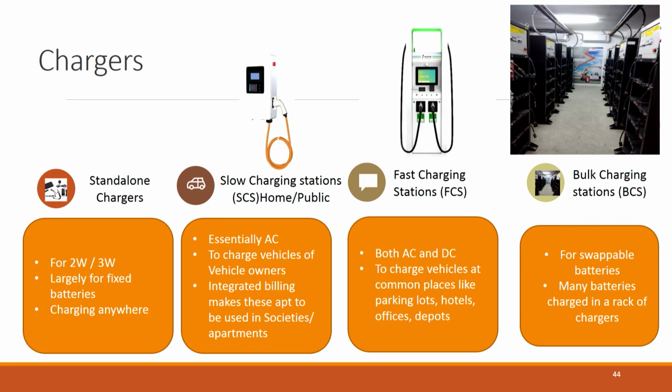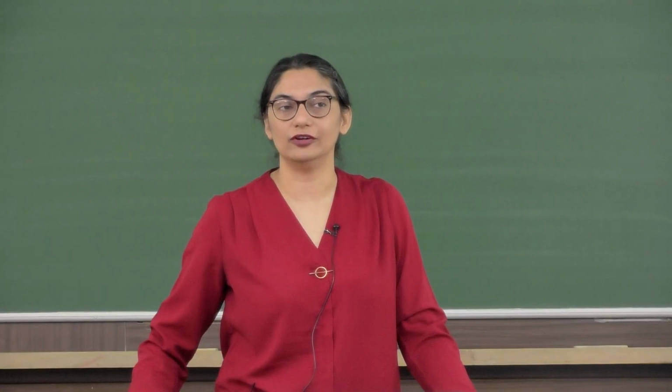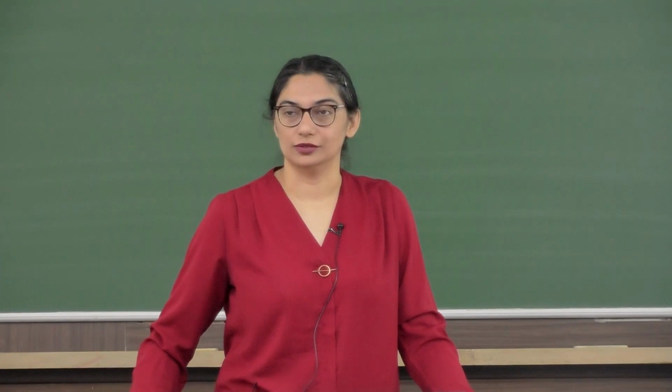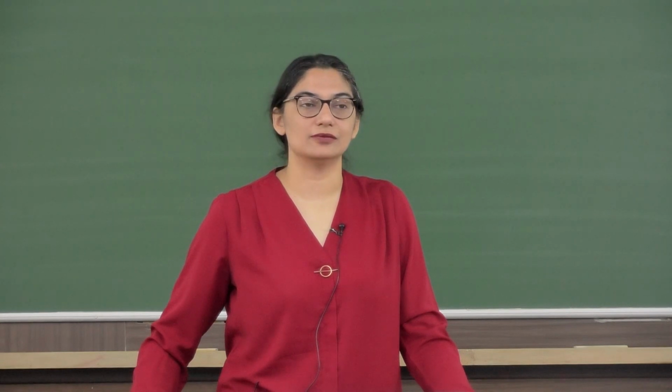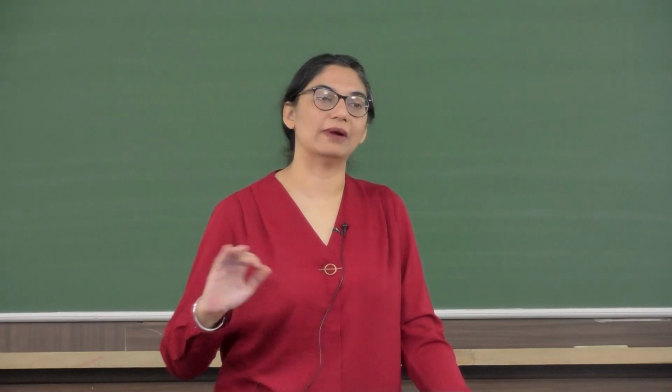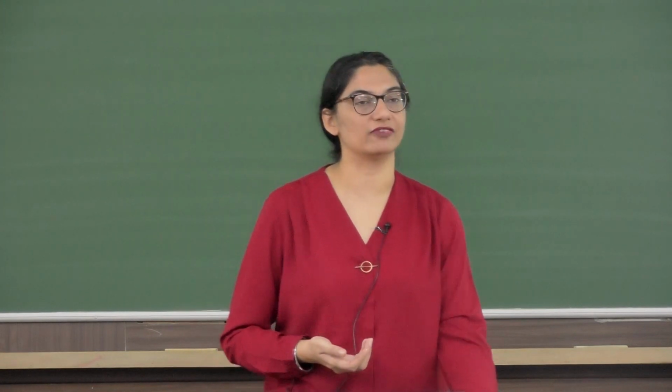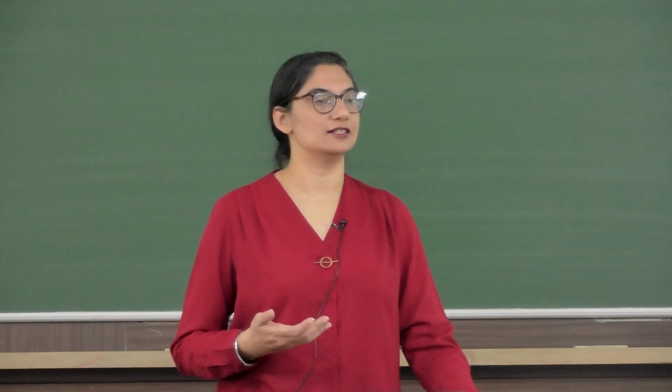But it also depends upon whether my charger is able to charge that battery at that rate or not. If my charger does not provide that kind of current, we call it a slow charger. So any charger that supplies less than 0.5 C, or for reference 1 C, we call a slow charger.